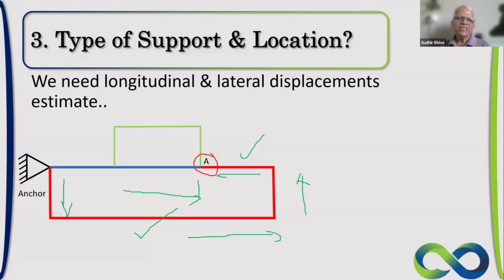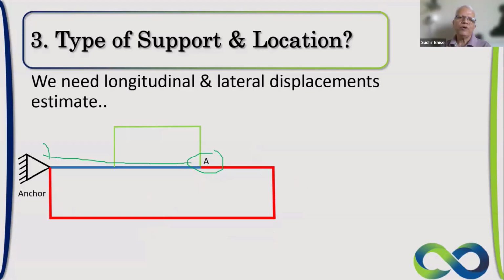So here I'm making a statement now that whatever layout you follow for reaching a particular location A, if you simply know the shortest distance from the anchor point to this point of interest, and you multiply by the expansion coefficient alpha, the displacement is going to be the same whether you follow the blue route, the green route or the red route. Let me explain again.